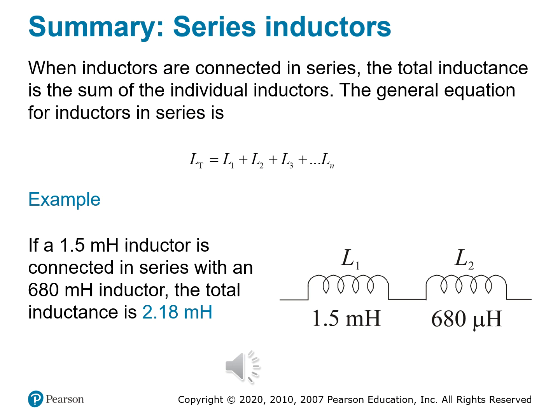And we don't have every single value of resistor available. But if you needed a custom resistance for a particular circuit to work optimally, you'd build a circuit to give you that equivalent resistance. So we do the same thing with inductors. We can't manufacture every single value. And so with just these values, we can combine them and make an equivalent inductance to get the one we need if we need something extremely specific.